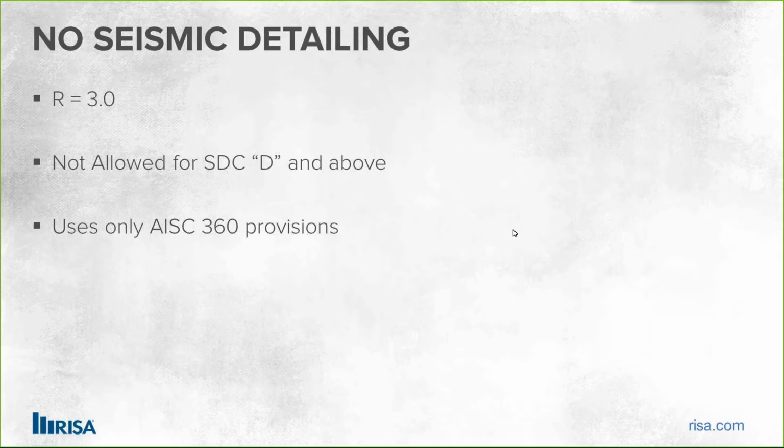And in this case, you can use an R of 3, and this allows you to get away with using only the AISC 360 provisions. So all these moment connections that we showed you here just now, with the exception of that reduced beam section one, could commonly be used in structures that are controlled by wind forces, for example, where we need everything to stay in the elastic range and we're not trying to force ductility into the system.